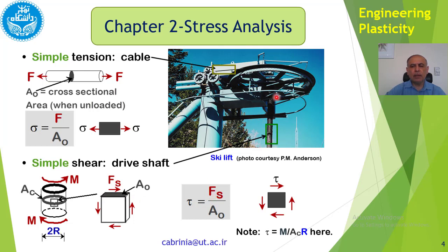Okay, this is due to the fact that one end is over here which is free, and one end is fixed down there. When the power is applied to this shaft, it tries to turn it, but there is a big load in here, big inertia, and so to drive it, it has to apply the power and the force, and then this shaft is under the action of torsion. Now then, let's see. Also here we can write tau like that. That's the torsion. That's the area, and that is the radius.